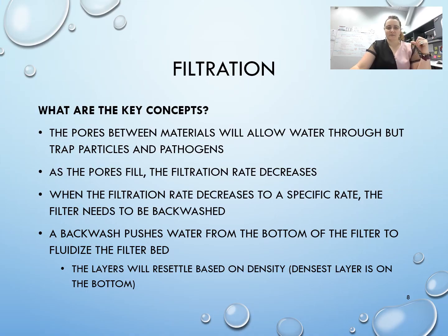Some key concepts related to filters. The pores between whatever material you're going to use in your filter have to allow water through, but they trap particles and pathogens. So normally we're talking about a very small pore size. You'd normally choose things like sand, because sand can be packed pretty closely together and it will pull those pathogens and particles out but let the water through.